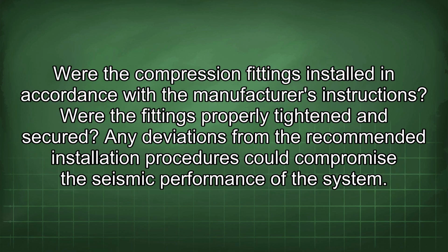Fifthly, assess the installation practices employed by the contractor. Were the compression fittings installed in accordance with the manufacturer's instructions? Were the fittings properly tightened and secured? Any deviations from the recommended installation procedures could compromise the seismic performance of the system.